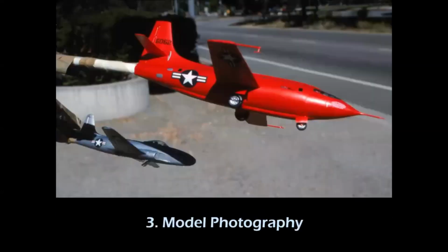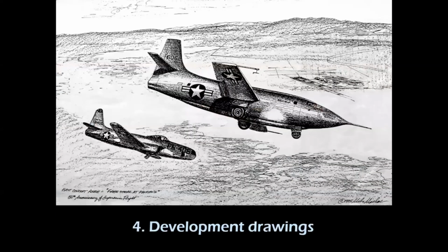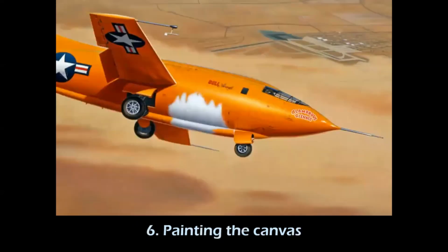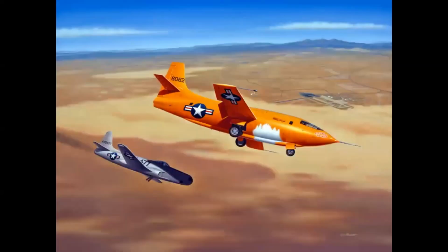Repair sketches. A sketch is frequently drawn for repairs or for use in manufacturing a replacement part. Such a sketch must provide all necessary information to those who must make the repair or manufacture the part. The degree that a sketch is complete depends on its intended use. Obviously, a sketch used only to represent an object pictorially need not be dimensioned. If a part is to be manufactured from the sketch, it should show all the necessary construction details.